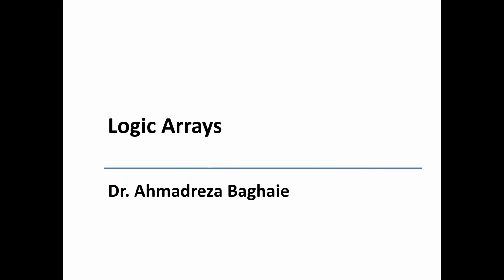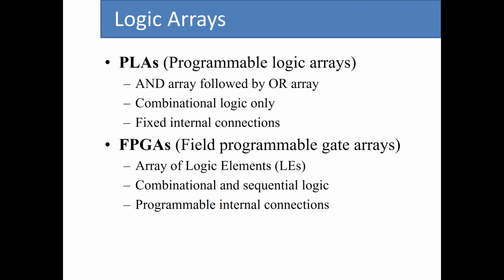In this video, I want to talk about logic arrays. There are two types of logic arrays that I want to cover here. One is the class of PLAs, or programmable logic arrays, and the other is the class of FPGAs, or field programmable gate arrays. PLAs are a bunch of ANDs followed by an OR array.